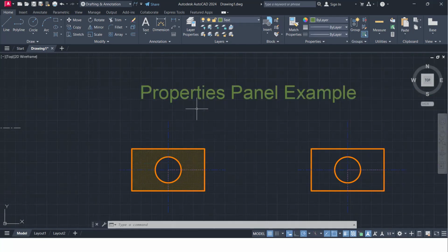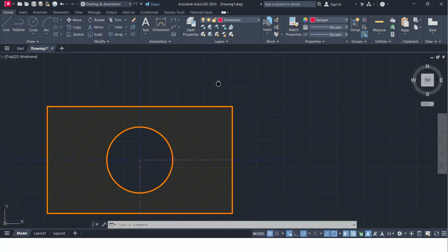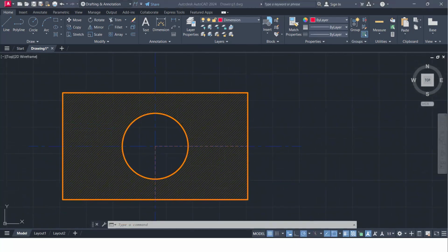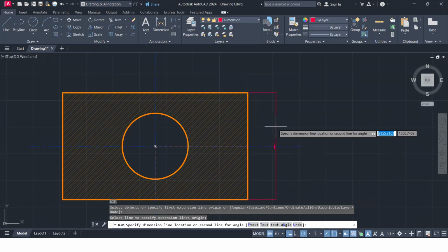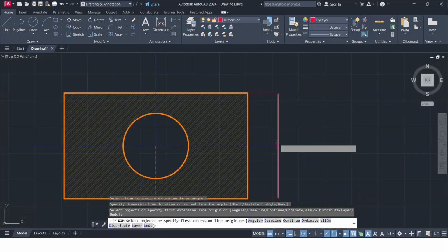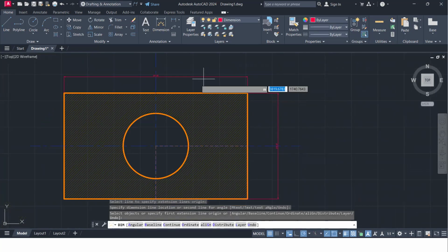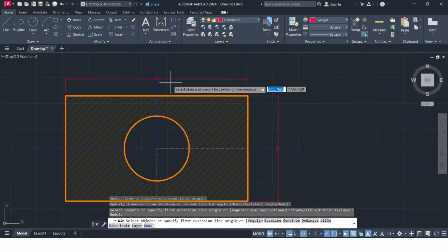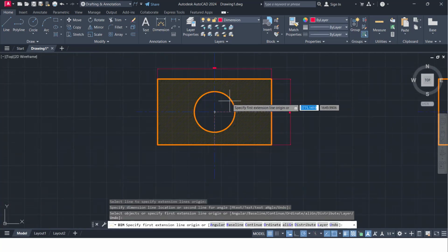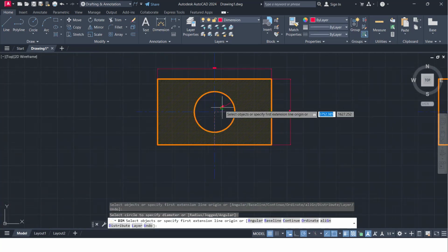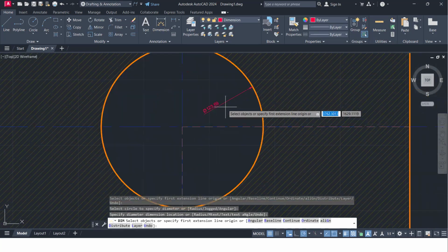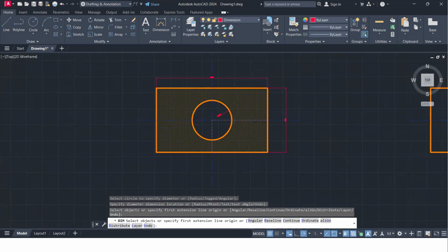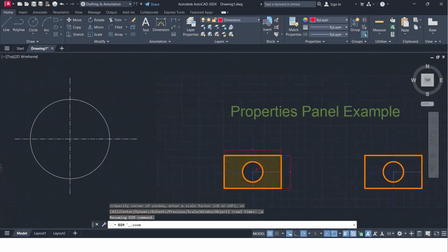Okay. Next, we want to apply dimensions here, then you can select dimensions here, and I want to write the dimension. For this purpose we use DIM, enter. Okay, and select this part, and this is your dimension. And then this color will be applied by the use of the dimension, right? Okay, and you can also use the dimension to increase the size or other things. This part will be told to you later.